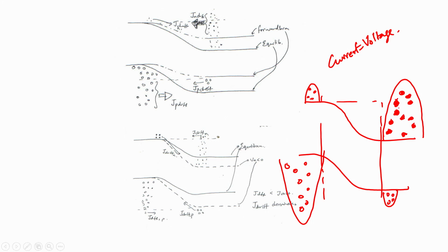Now, if you look at the electrons on the N side, they are trying to climb up the hill. If you recollect, the band bending diagram is drawn in a manner where it's easy to understand the motion of the electron and hole. The electrons like to run downhill, the holes like to run up the hills, and if you increase the potential the energy levels go down, and if you decrease the potential the energy level goes up. That is the way you imagine the band diagram.